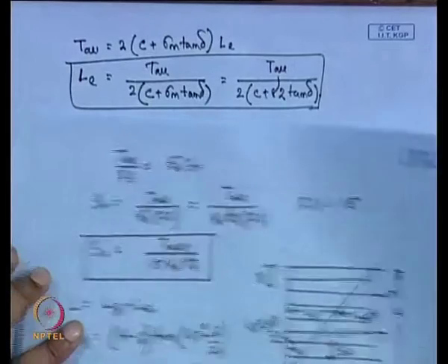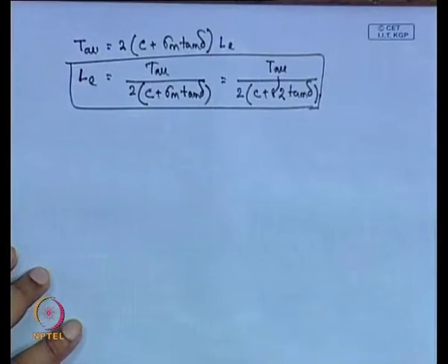So, that means if I put the spacing which is required at the bottom of the reinforcement and the length which is required at the top of the reinforced wall, that is, the spacing required at the bottom of the reinforced wall and the required length at the top of the reinforced wall, then the design is safe.